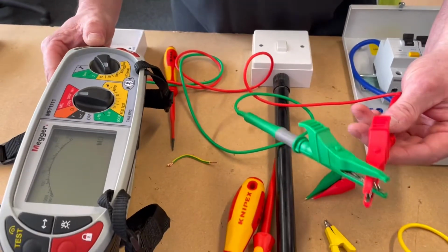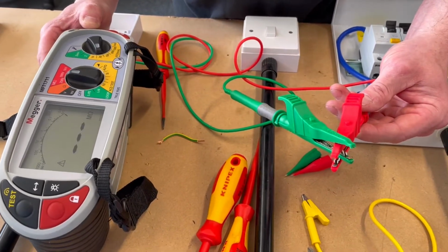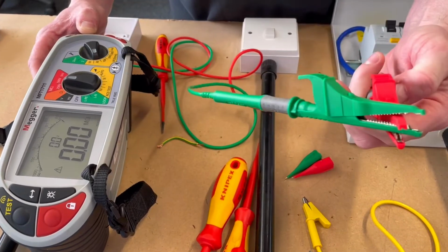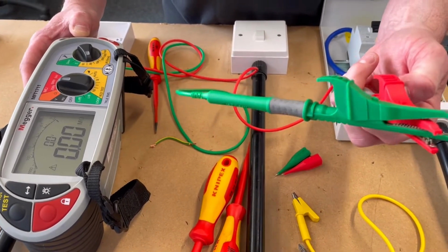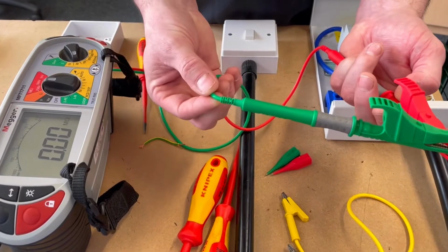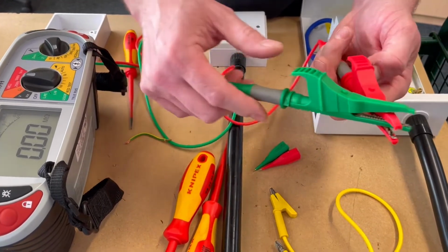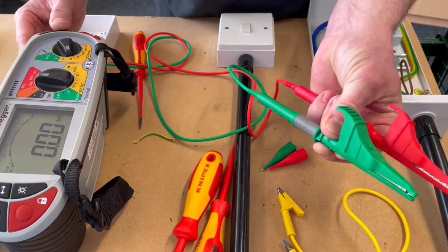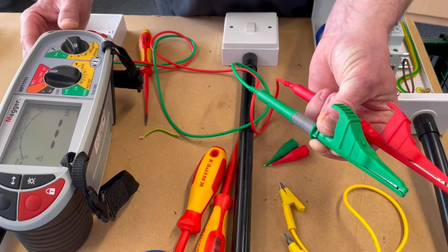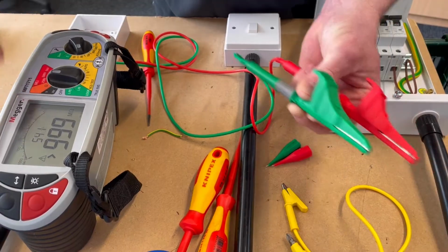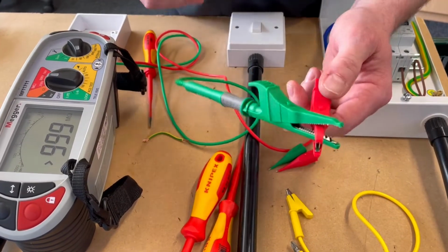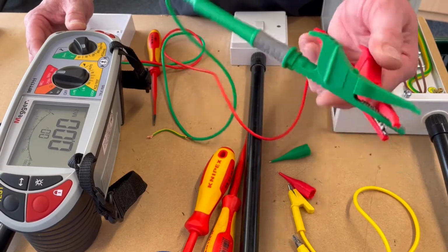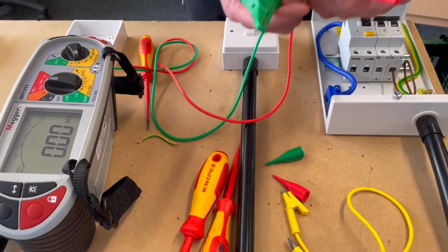I'm going to press and hold my test button now. It doesn't automatically do this test. And as they're joined together, I've got 0, 0, 0, in other words, a dead short, meaning that the leads are in good condition. If these leads were snapped, and again, I've done a little video on them, and they tend to snap around here, what you end up with is the equivalent of it being broken. If I press and hold the tester again, you get a reading greater than the machine can read. So if we short them together to prove that they're not broken, we expect to get 0, or a dead short, for that reading. So our leads are good, and we're ready to test with these.